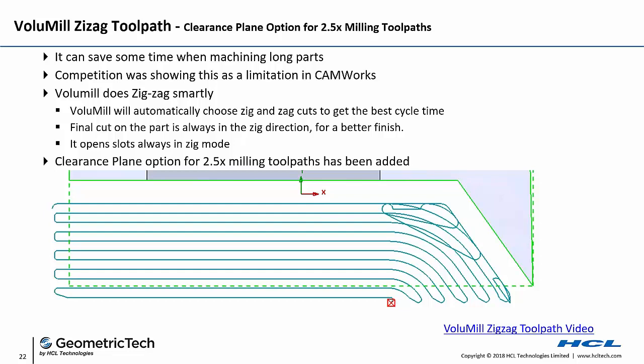The final cut on the part is always in the zig direction, you would say, for example, climb mill direction for a better finish, and it opens up slots always in the zig mode as well. So just a nice enhancement now that's been added for volume mill specifically. And let's just take a quick look at that one.